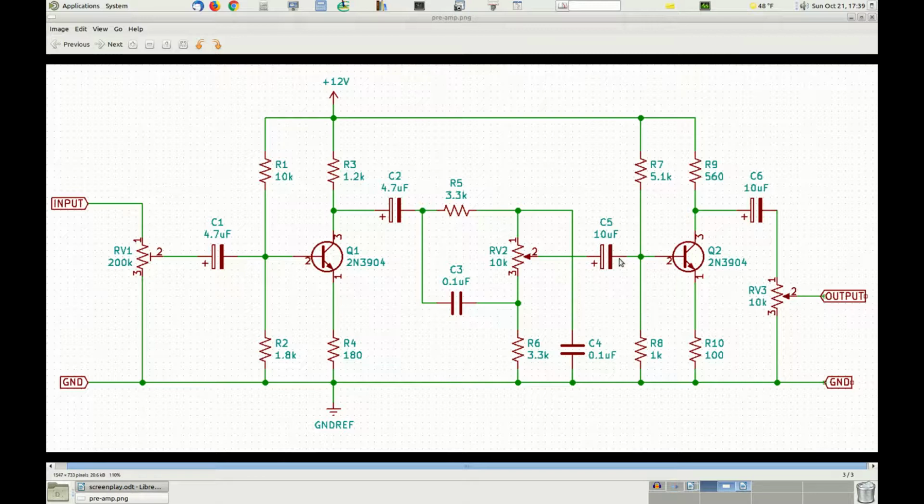The signal at the cursor of the potentiometer RV2 is then passed to the next stage of the preamp, where it gets further amplified. This stage is similar to the first one. Its main purpose is to bring back the overall amplitude of the signal after it has been attenuated by the brightness filter, so as to provide a signal high enough to correctly pilot the power amplifier. Potentiometer RV3 regulates the amplitude of the output signal, so it basically provides a volume control to the audio.